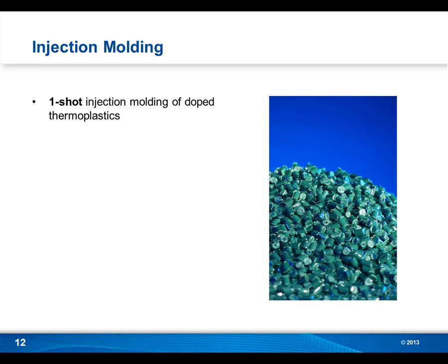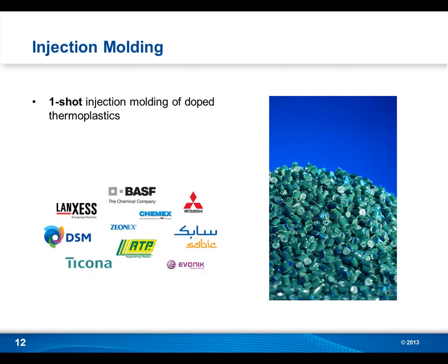So your conductive structure is then put on with the laser later. Now, these grades are available from all the major plastics manufacturers in all major grades of plastic, from polypropylenes to PC/ABSs to nylons to LCPs. So there's quite a wide variety that you can use in the design process.